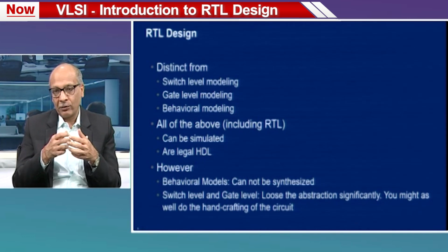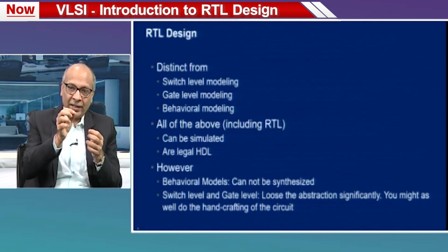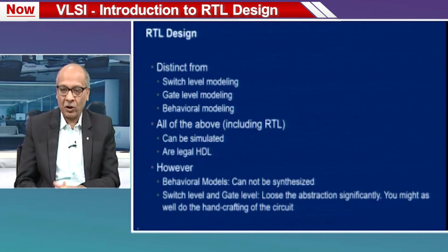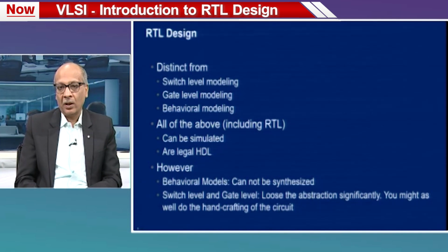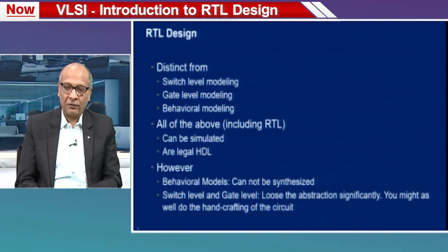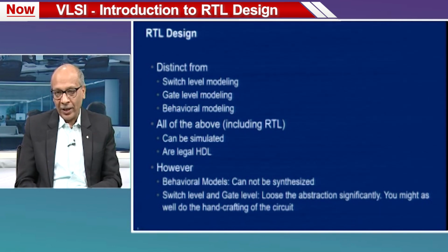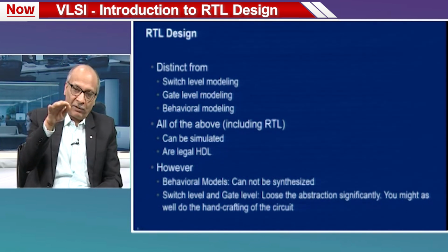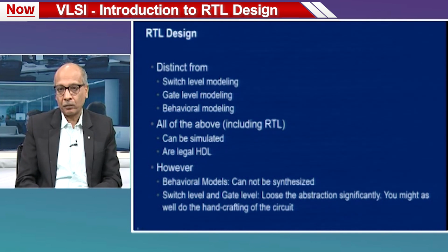Gate level modeling is when you write something in terms of the AND gate, the OR gate, the D flip flop, and the XOR gate, and so on, right. And the behavioral modeling is a still higher level of abstraction, where you describe everything at a very high level of algorithm, almost at the same level as, say, C. So, RTL design falls somewhere in between. It is between gate level modeling and behavioral modeling.